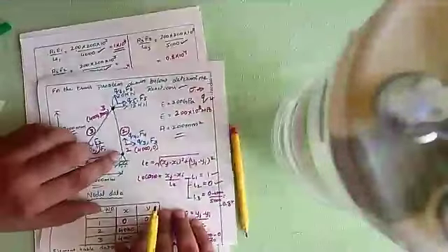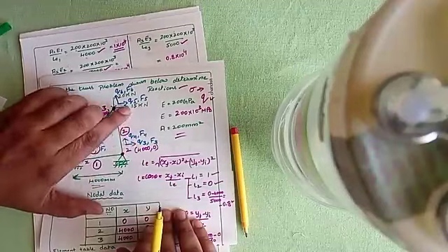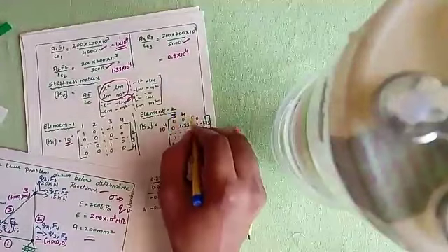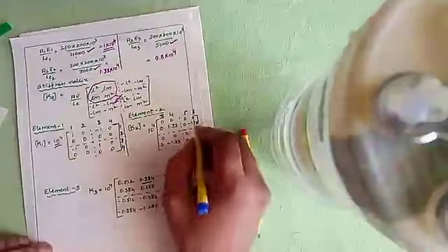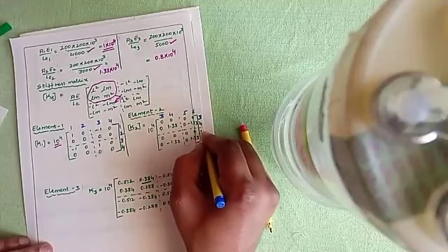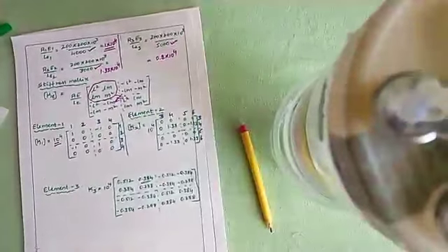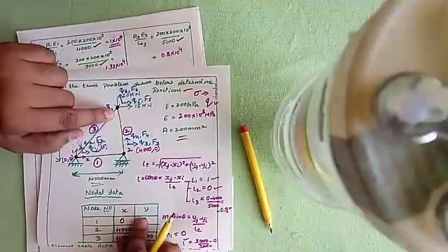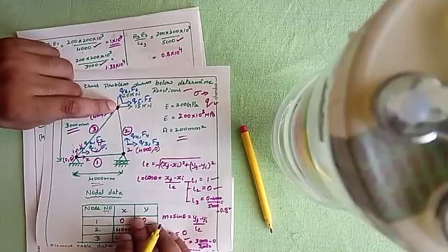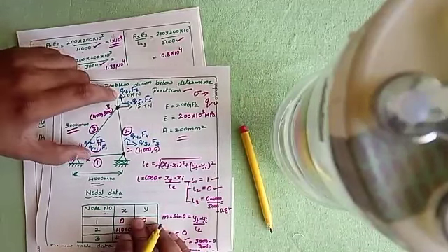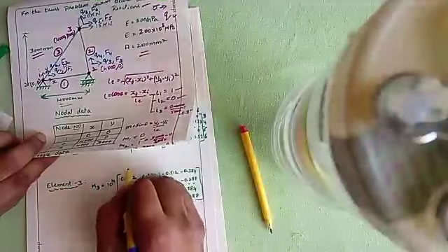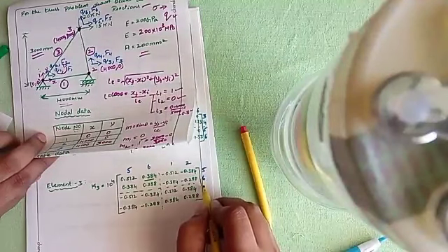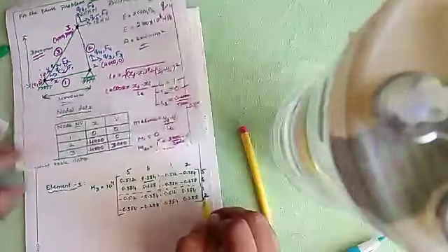For your element number 2, what are the degrees of freedom? 3, 4, 5, 6. In the same sequence, you're going to start. In spite of writing Q3, Q4, Q5, Q6, I am writing 3, 4, 5, 6. Once you have done this, next for your element 3. Now, this is where you need to be careful. You are moving in a counterclockwise direction, so that's what I told. For your element 3, this is your initial node, so you're going to start with 5, 6, then you're going to come to 1 and 2. So 5, 6, 1, 2.